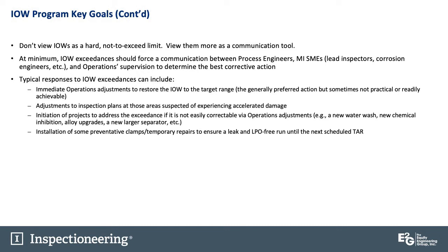So typical responses to IOW exceedances can include immediate operations adjustments to restore the IOW to the target range. That is the generally preferred action that we like to see, but sometimes that's not practical or readily achievable, or maybe just not economic for the refinery.